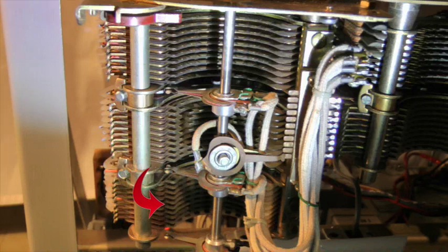Each bank assembly has 3 tiers: lower, middle, and upper. The lower bank tier contains the tip and ring terminals for line circuits numbered 00 to 99. The middle tier contains the tip and ring line terminals for line circuits numbered 100 to 199. And the upper tier contains the sleeve terminals for all 200 line circuits. Each bank tier has 10 levels of terminals. The levels are numbered from the bottom up, 1 through 9 and 0.